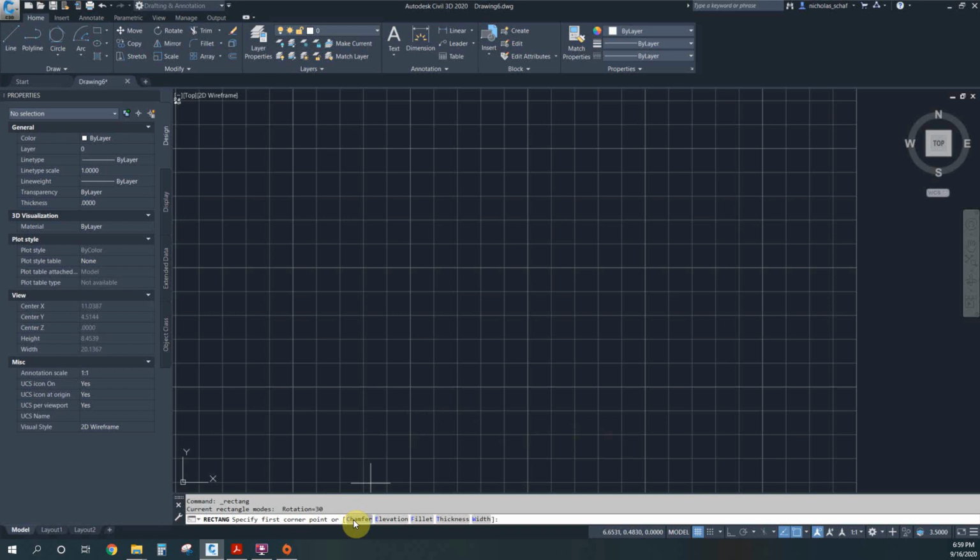So like along your desk, sometimes you will see that where it is flat on the top of the surface, and then it's flat on the corner, and then it goes down. So I'll demonstrate that here right now. So I will click on chamfer, and I will do 0.15 for my chamfer distance, and 0.15, and you can have them in different directions.